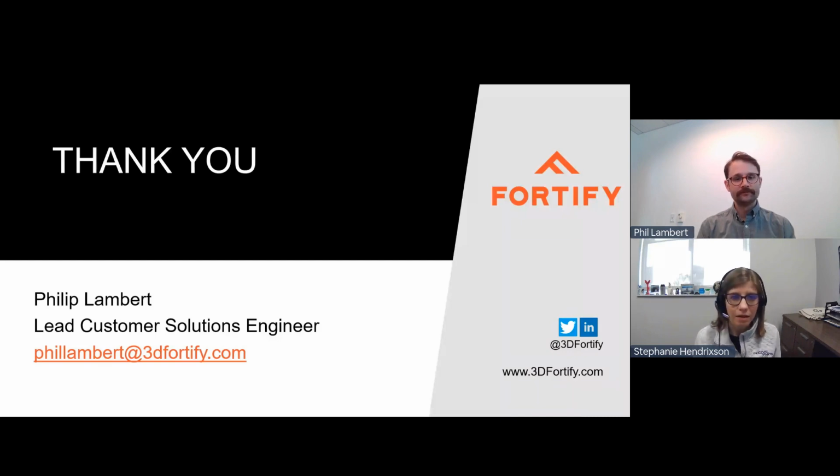Got it. What is the upper viscosity limit for your system? Another great question. There are several ways to answer that. We have processed materials as high in viscosity as 10,000 centipoise, and I think in some cases we've done quite a bit higher than that. To be able to circulate it is a different question, right? So we can print using CCAM to heat and mix, but in order to be able to do that, you need to be able to have it flow at room temperature.